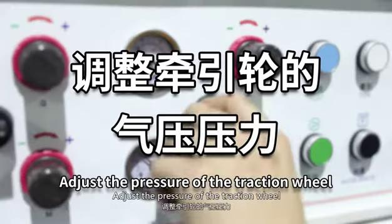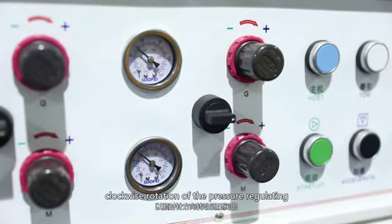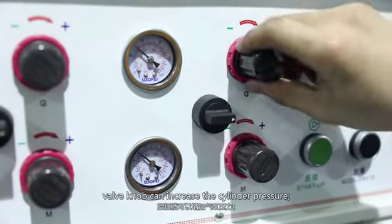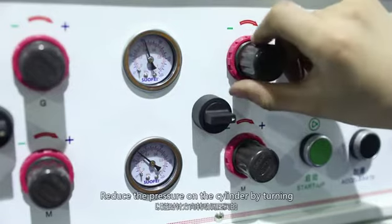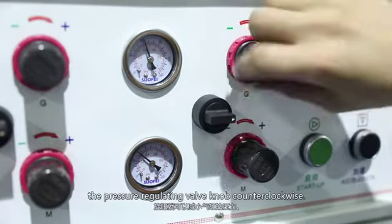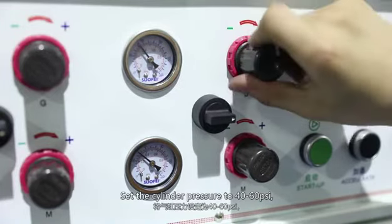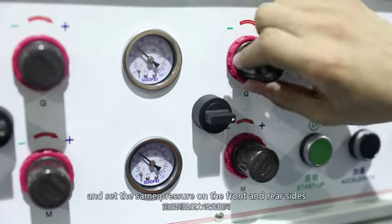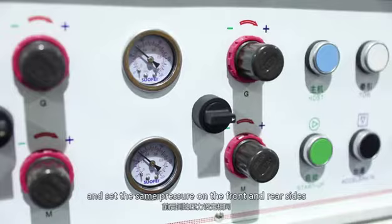Adjust the pressure of the traction wheel. Clockwise rotation of the pressure regulating valve knob can increase the cylinder pressure. Reduce the pressure on the cylinder by turning the pressure regulating valve knob counterclockwise. Set the cylinder pressure to 40 to 60 psi and set the same pressure on the front and rear sides.